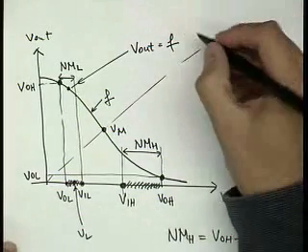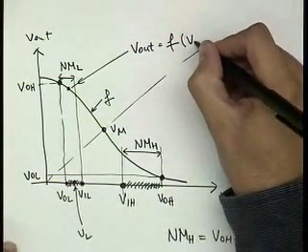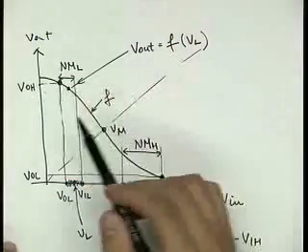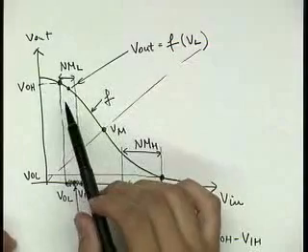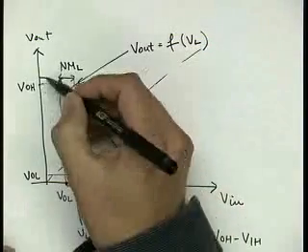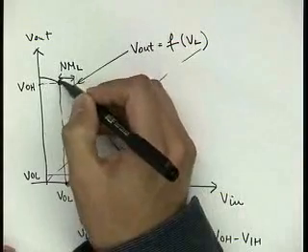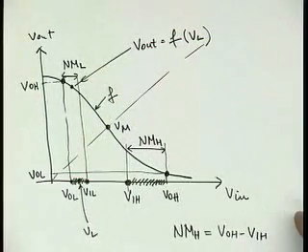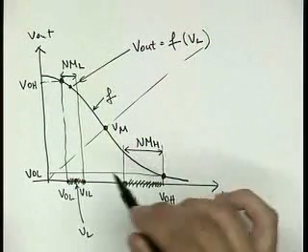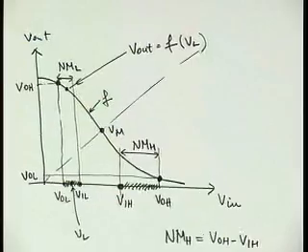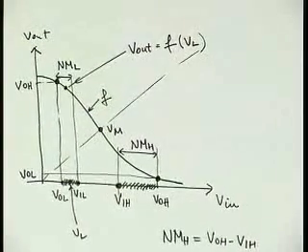So it's some low that is interpreted as logic 0. So it's a function of VL, and then as you put these gates in a chain, you would end up with a fixed voltage, even here at VOH. It will converge, eventually settle down. So understand these definitions. It's kind of important to realize. All right.